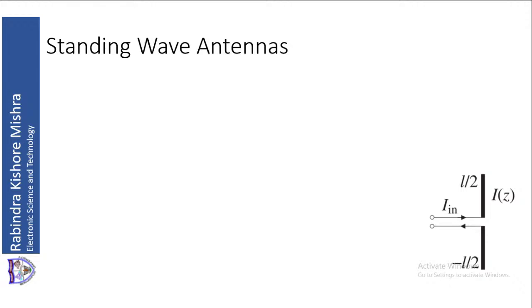Up to now, we discussed the Hertzian dipole antenna, and we said these are fixed antennas, but in practice, we can say a Hertzian dipole antenna is an antenna whose length is less than lambda by 50. If we have this type of antenna, the power radiated by this antenna is very small, so it has no practical application. So now let us consider antennas which have practical application.